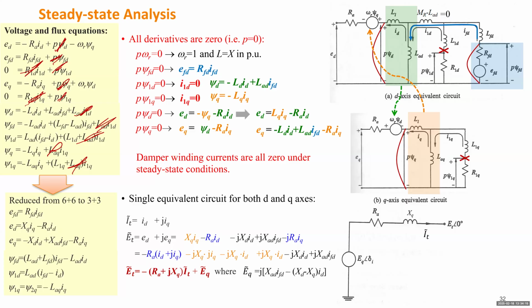If you really want to dig into why this one is not XD, you can go through the same approach. But in my approach, I try to create one term, which is like terminal current multiplying some reactance. So here I assume that reactance is XQ. You can assume that one to be XD. Then you will see what will be the last term.